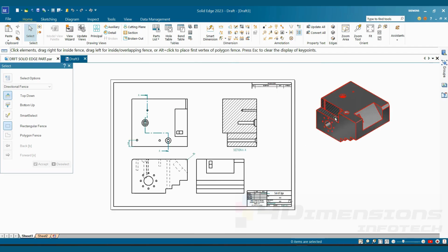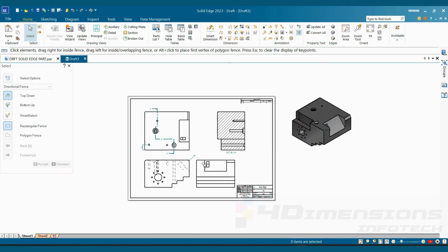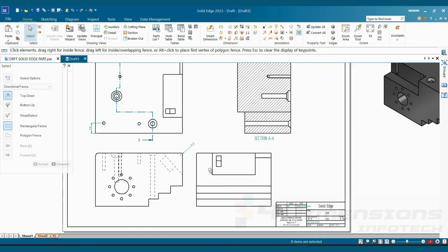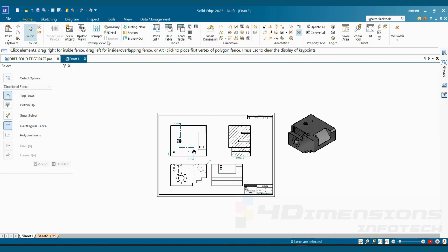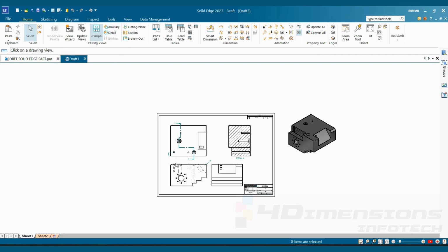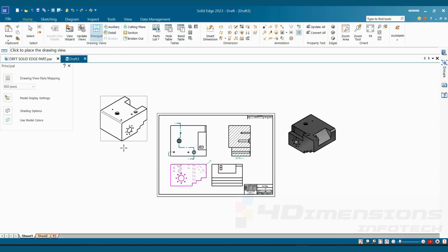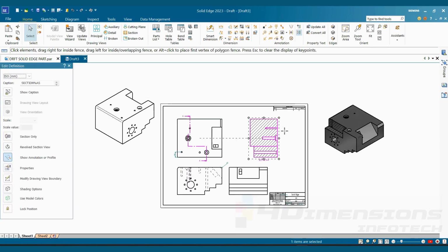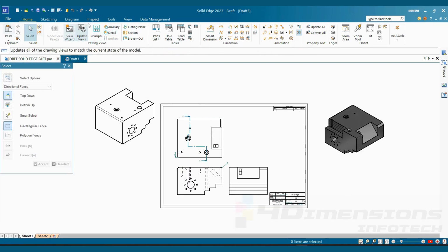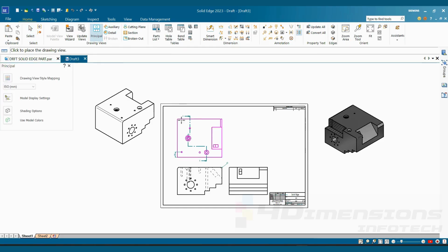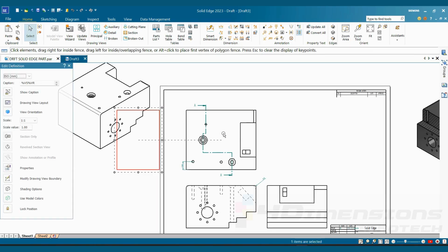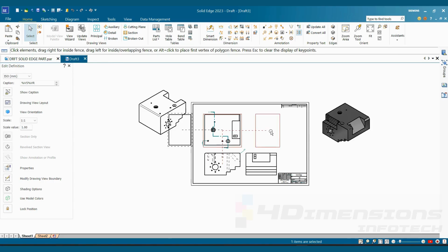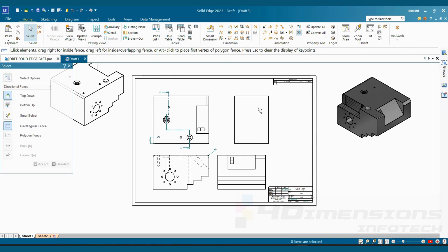So in this way, you can go for these cutting sections. Again, if I want to go for this view option, I'll take one more principal view here as an auxiliary view only. I'll place it somewhere here. Now for that I need one more view. I'll take a principal view, left side view of the top. I'll place it at the right side. Even though it is the left side view, I'm placing it at the right side. Hidden lines are not visible, that's why it is showing a plain rectangle here.